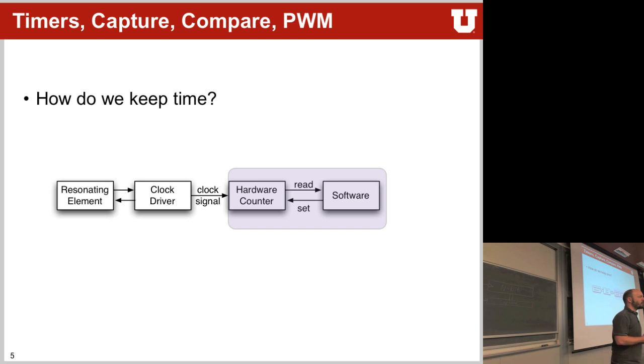The second thing was a compare. What's a compare? Well, it's just yet another register that's in here. And this time, instead of being filled from your counter, you fill this register with the time, right? And then what the hardware does is it compares the value in here with the value of your counter, and once they match, it will do something on the output.